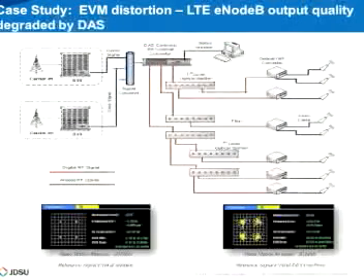And the reality was that in many of the tributaries of the DAS system, we actually found degradation in the signal quality. This is something that is prevalent and can happen within a DAS system. Not only can it happen to the signal quality, but we've also seen where cables have been swapped, meaning that you don't have the MIMO that you expected. There are different levels of impact that can have on the end user, or simply a diversity alarm where you may be replacing the wrong antenna.